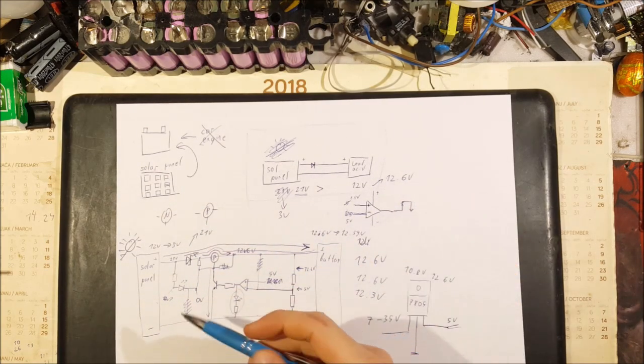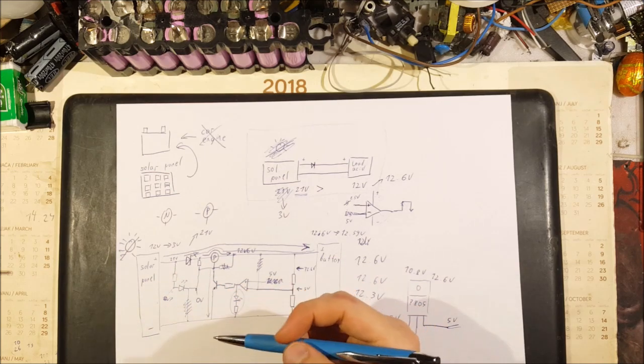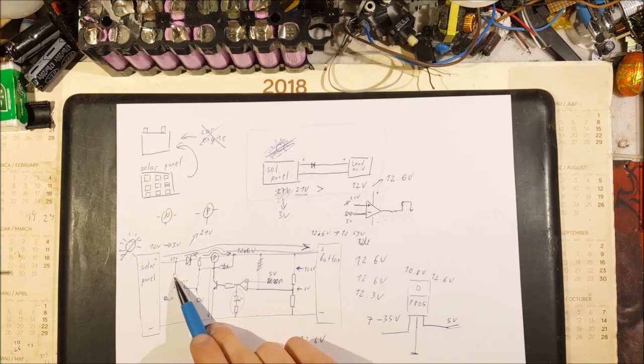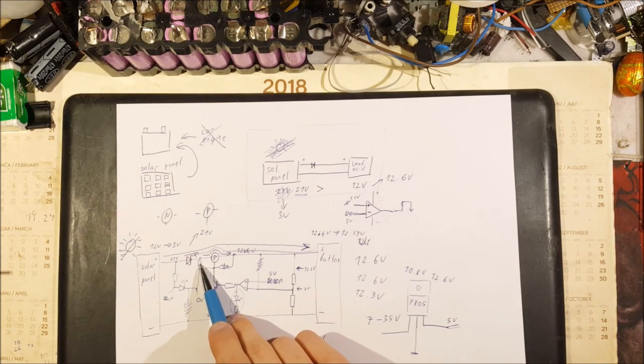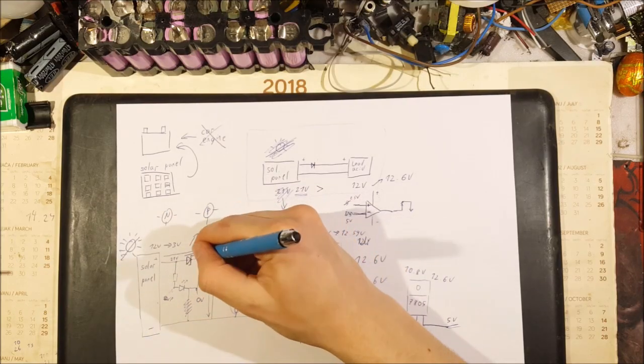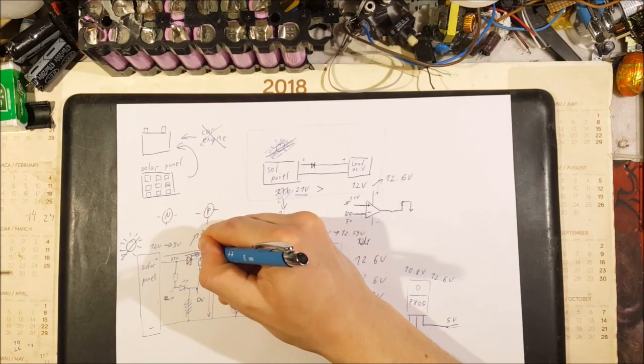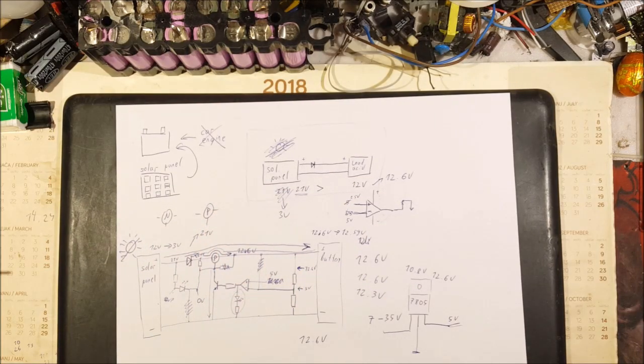But now the difference between this point going through the resistor, through the diode, and through the resistor is essentially 0, because there is 21 volts here and 21 volts here. That just means that our LED will no longer illuminate when the charging is finished.